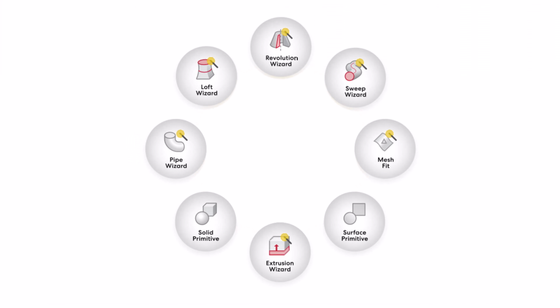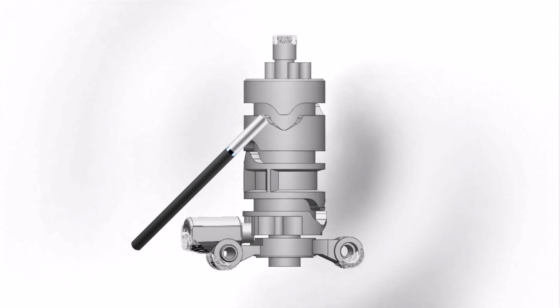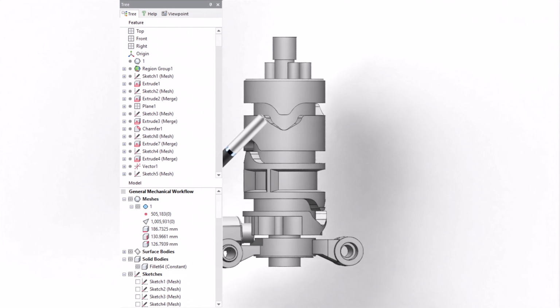The modeling wizards are a set of commands that help DesignX users extract CAD features of complex geometries from 3D scan data regions with just a couple of mouse clicks. And because it's DesignX, the sketches and features created by the wizards can be edited by the user both immediately in the software or in other CAD software like SolidWorks, NX, Creo, and Inventor. You have full control over where the feature is located, how it's oriented, and even how to balance sketch complexity